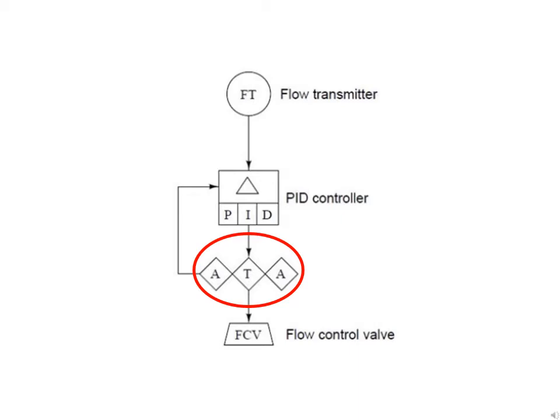Apart from the basic PID controller function, in the example below, we see a transfer block and two manual adjustment blocks, providing a human operator the ability to separately adjust the controller set point and output manipulated variables, and the transfer between automatic and manual modes.